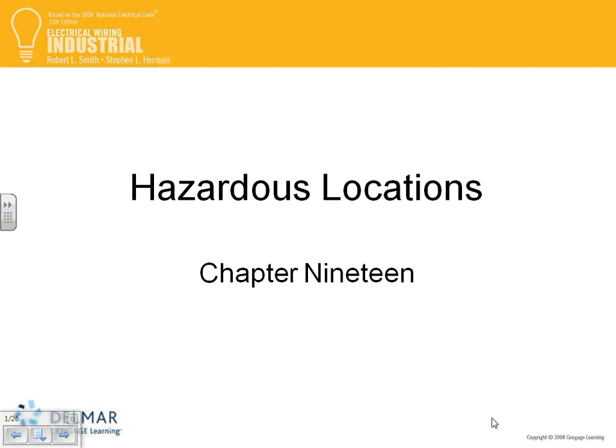Class 2, summarized in one word: combustible dust. And Brad, there's a difference between flammable and combustible. Flammable means the flash point for the gas is lower, so a gas can ignite at a lower temperature than a dust. That's why they use the word flammable and the word combustible. If anybody's interested, there is a lot of stuff about them, but all you're interested in right now is the word flammable. Anything flammable can ignite faster at a lower temperature than combustible. That's why they rate them. So we have combustible dust. Any dust that could be combustible, they put in class 2.